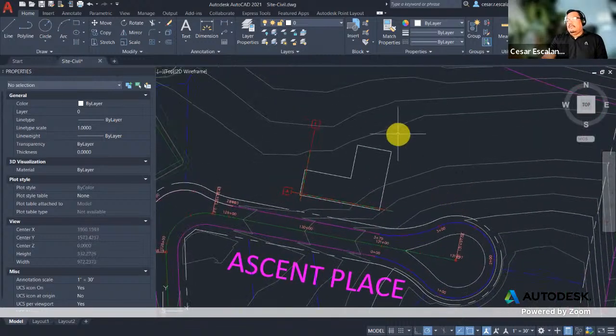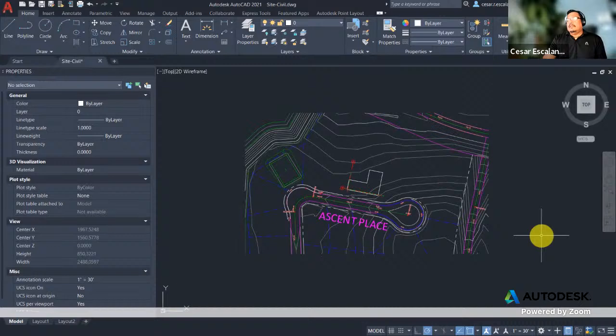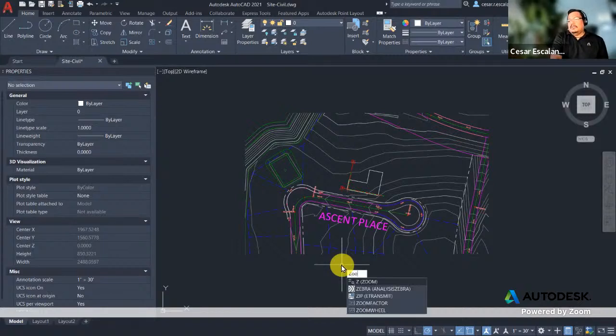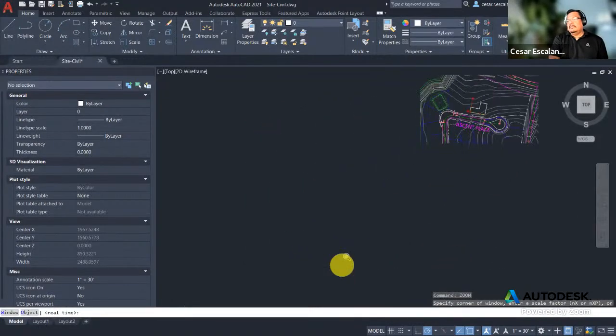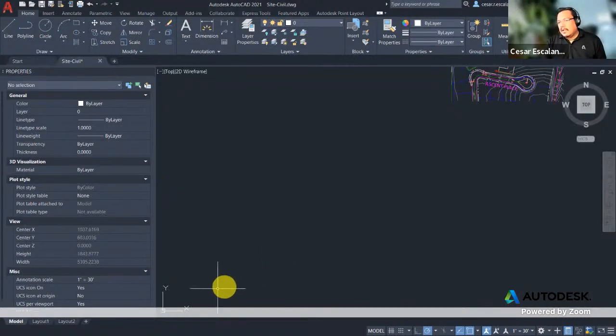And again, the elevation of my building is 60 feet above sea level. And I have to clean the AutoCAD file. Cleaning the file means to verify the extent of the CAD file. So for you AutoCAD users, there's a command in AutoCAD called zoom extents, and zoom extents will display the full geometry.